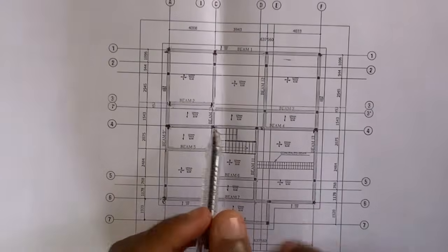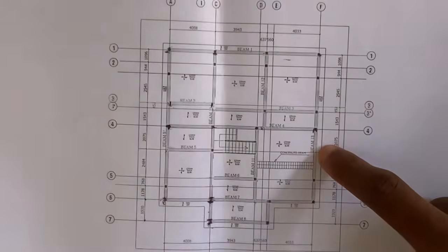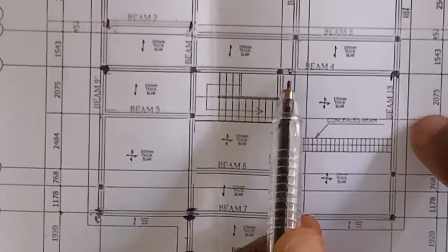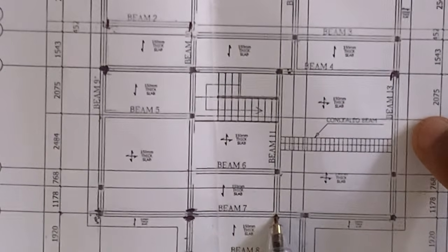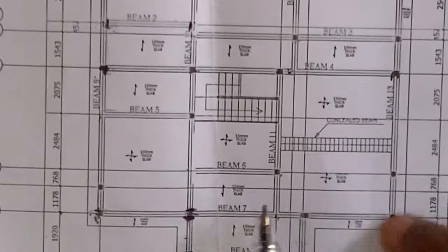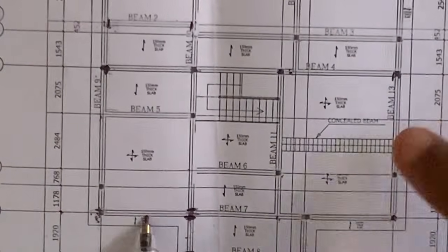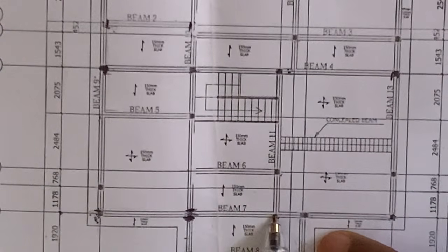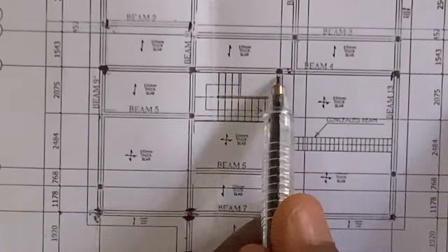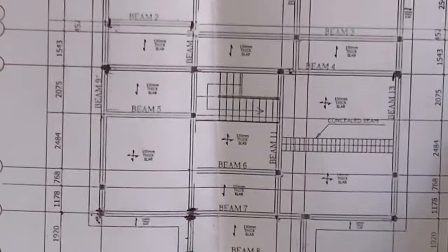So where is beam 11? As you can see, this is beam 11 from here to this point. If you look at it closer, beam 11 is from this column down to this point of intersection here. That is beam 11. Now, if you remember, we've already measured for beam 4 and beam 7, meaning that beam 11 is intersecting beam 4 and beam 7. So now we need to determine the total length of this beam 11, which is from callout 4 down to callout 6, sorry.